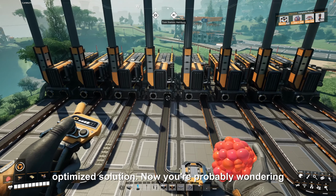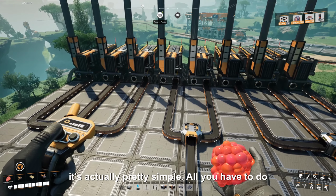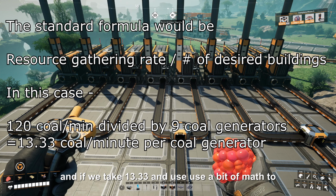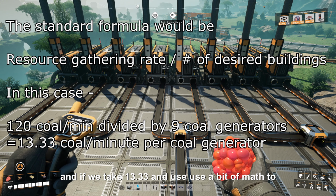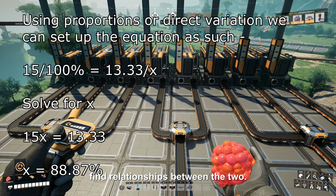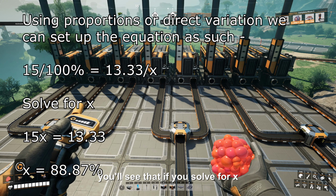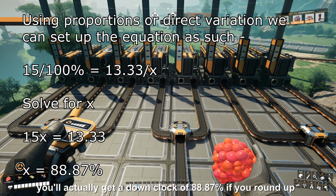Now you're probably wondering, how do you determine the downclock? Well, it's actually pretty simple. All we have to do is take 120 divided by 9. And what that gives us is 13.33. And if we take 13.33 and use a bit of math to find relationships between the two, you'll see that if you solve for x, you'll actually get a downclock of 88.87% if you round up.